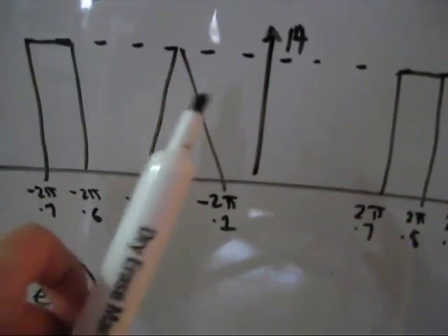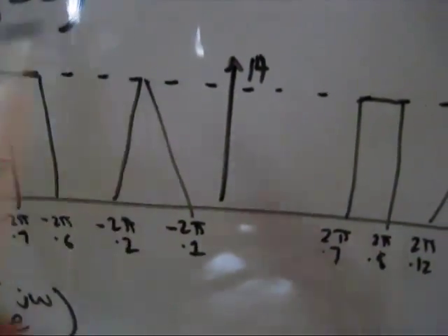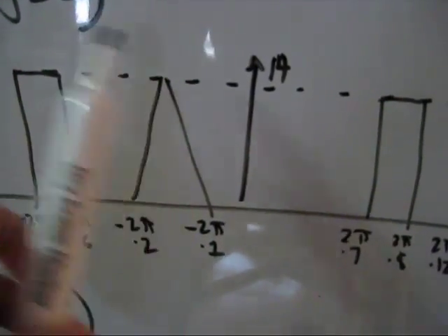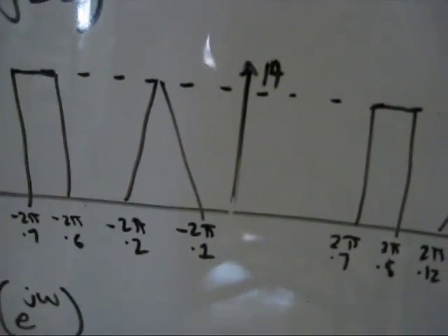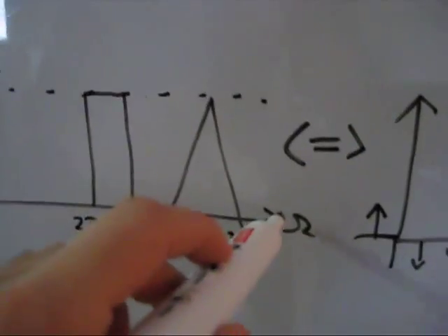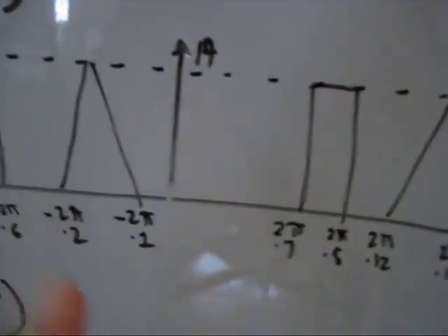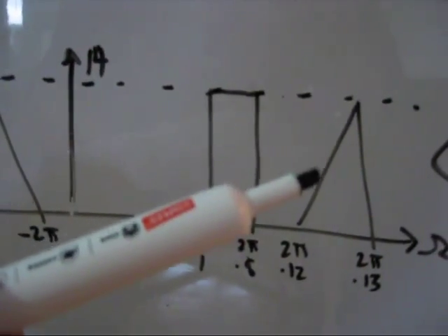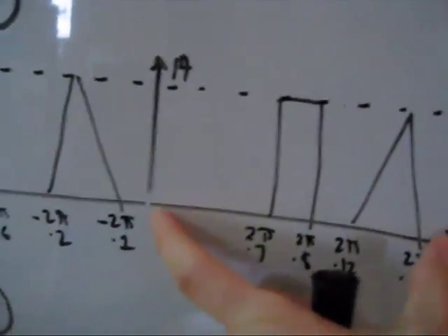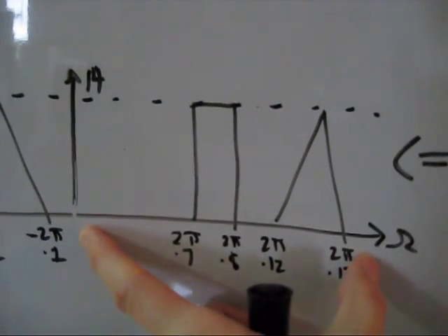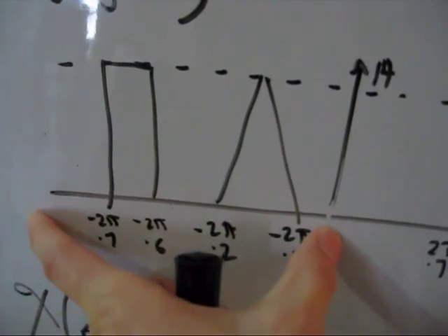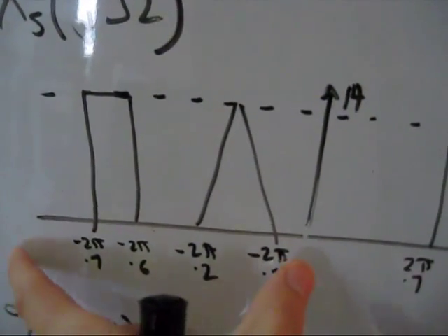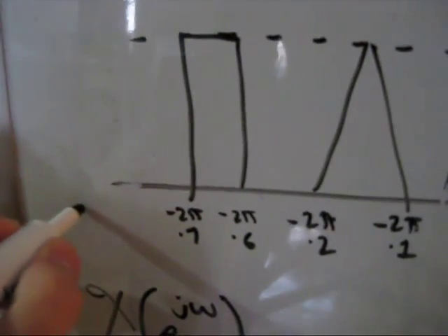So the thing is that this is a replica. These are frequency components that we do not want. These are lower frequency than these. If we're not looking at the additional replicas, because there's going to be replicas every 14 hertz. Okay, that's the other important thing. We sampled at 14 hertz, so there's going to be replicas every 14 hertz. So this was the original part that we sampled, right? 0 to 14. So if we take that and shove it over here, bam. We get our first replica, right? So this over here, that goes off to...